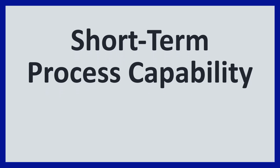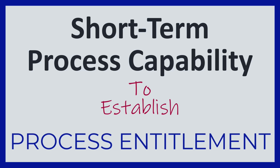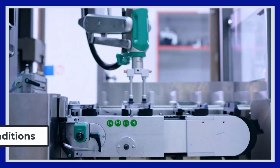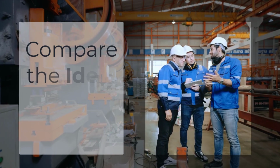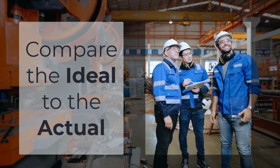Short-term process capability studies are done to establish the performance entitlement of any manufacturing process. This short-term type of capability study measures the process under ideal conditions. The value of establishing this process ideal is that it can be compared with the actual long-term performance of a process, and hence be used to identify process improvement opportunities.